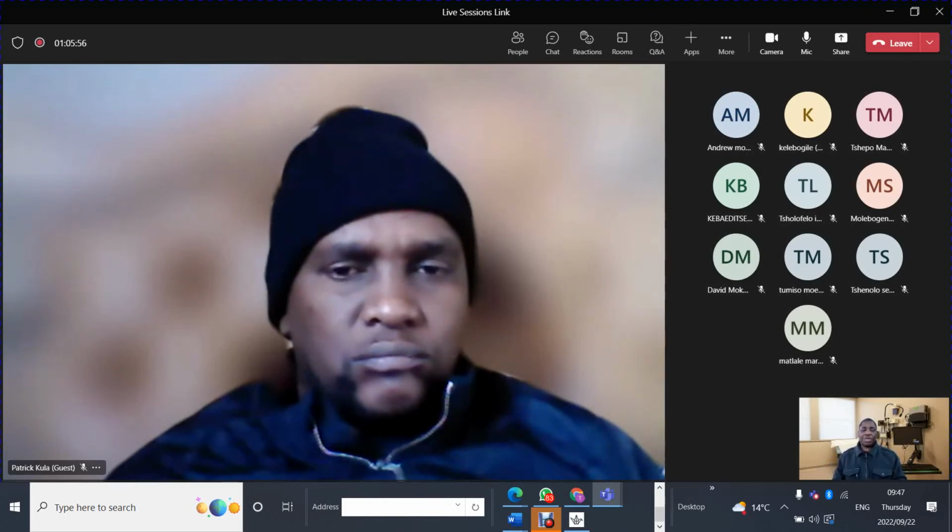So back to your question. When using electrosurgery, you do not want current to flow from the patient to ground. It will lead to electric shock, and in this case, it will be macro shock hazards. So you're exposing the patient to a shock hazard, exposing them to burns, because the site where that current will exit the body of the patient to ground will create heat and will burn the patient.